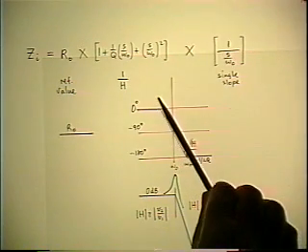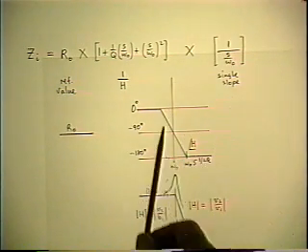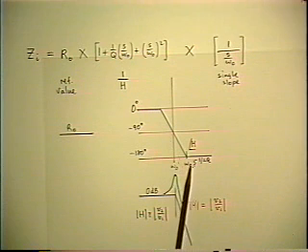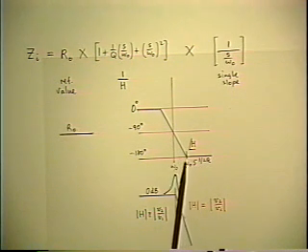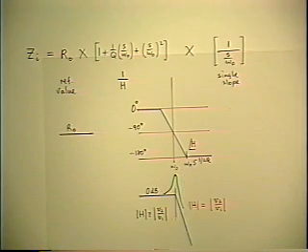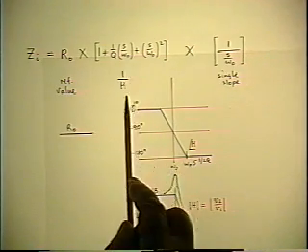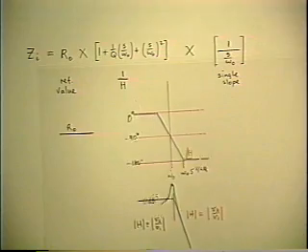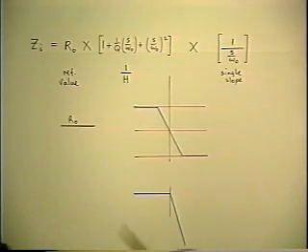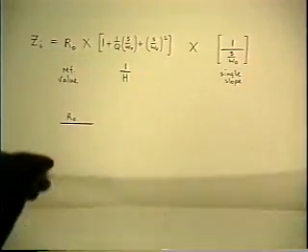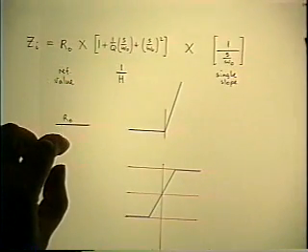So we get a single phase transition placed by choosing the intercept frequency at 1 over 2Q times the corner frequency. Okay, but we want not H, we want 1 over H. So I can take away the detail, and 1 over H is the vertical inversion of that, or turn it upside down.